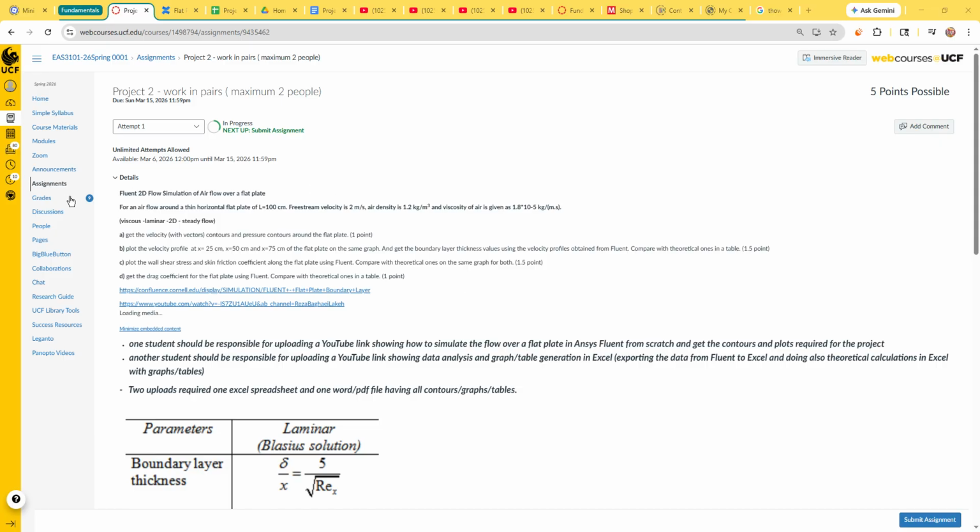Put on the sizings from the side so it gets smaller there, as you can well see. Put the name selections over here. I believe that's everything important here. Name selections: airflow is the main body, and then the size, inlet, outlet, plate, and far field pressure. Far field pressure is this top portion, whereas plate is the bottom.